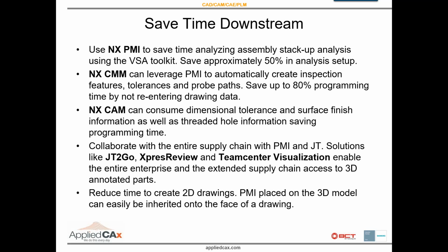NX CMM can leverage PMI and bring in tolerances, surface finishes, and can save your programming time by up to 80%. That can be quite significant if you're in a place where you're inspecting a large majority of the parts that are coming in. NX CAM can consume dimensional tolerance and surface finish information as well as the threaded hole information, saving programming time.